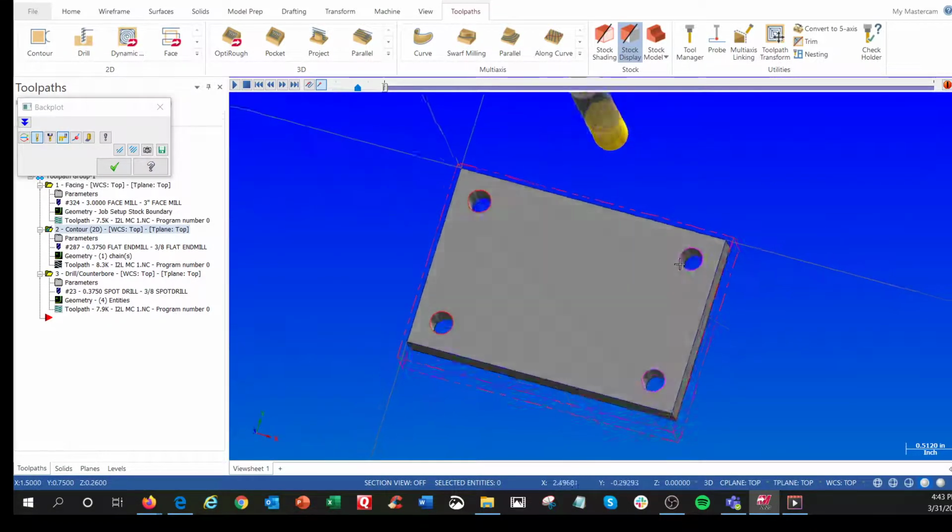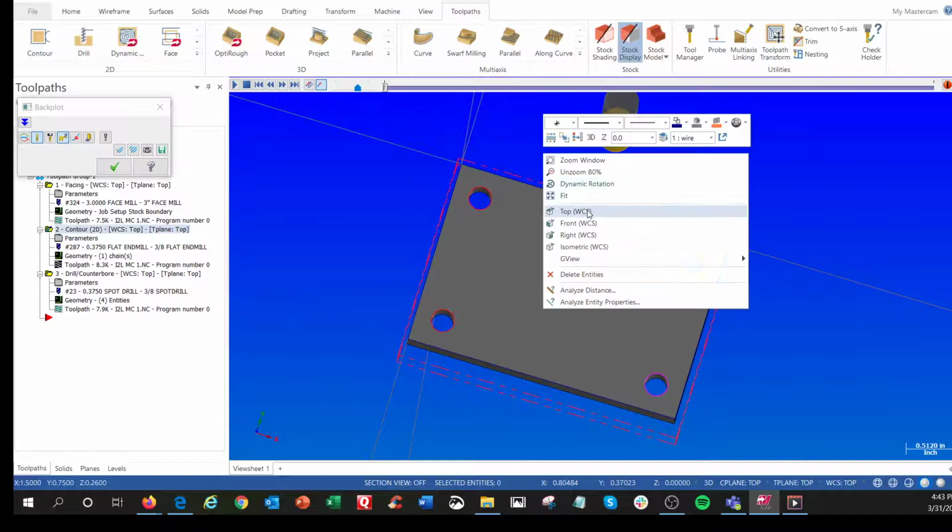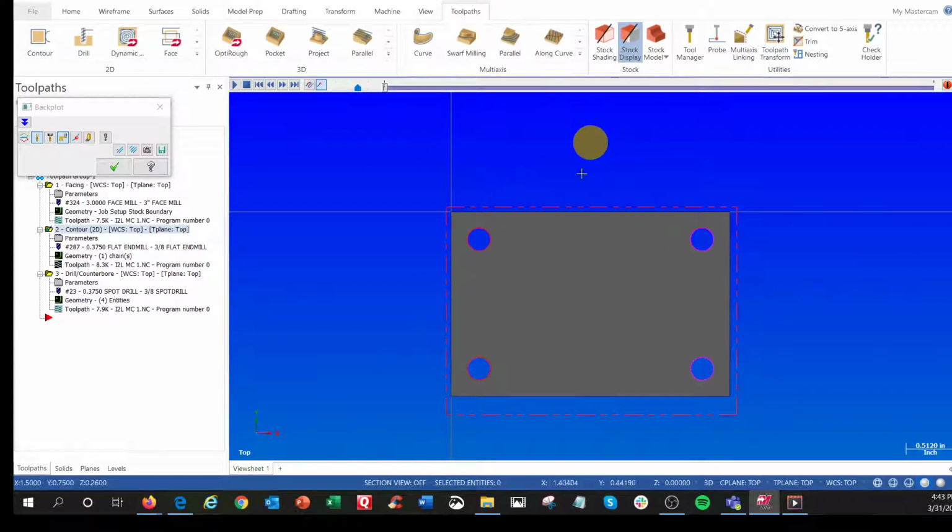And then we're going to navigate around this. But if we're using the print dimensions, that'll mean the center of the tool will be right there, and that would make this part way too small. So we're going to use the print coordinates, and we're going to use cutter compensation. We're going to put that diameter or radius in the geometry information in the tool offset page.